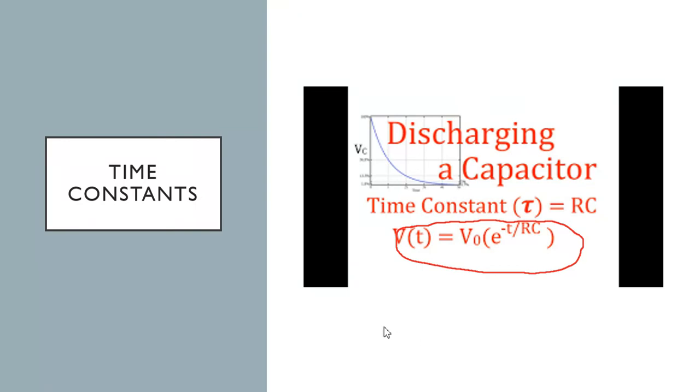And that's because the voltage is going down, not up. So either way, this area is giving us that percentage. And then we take that percentage and we multiply it by the total, and that's how much voltage is there at this point, right? When we're discharging, in parentheses, it's e raised to the negative time divided by the time constant.